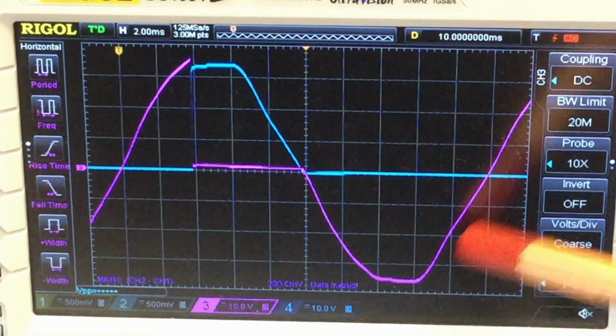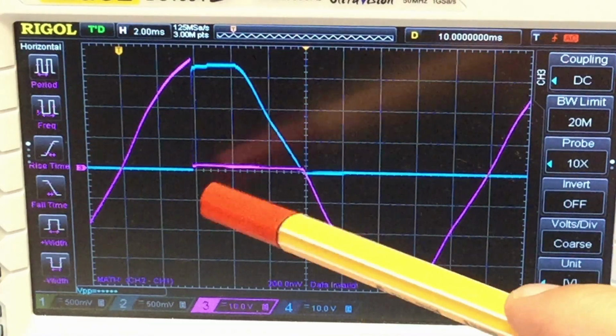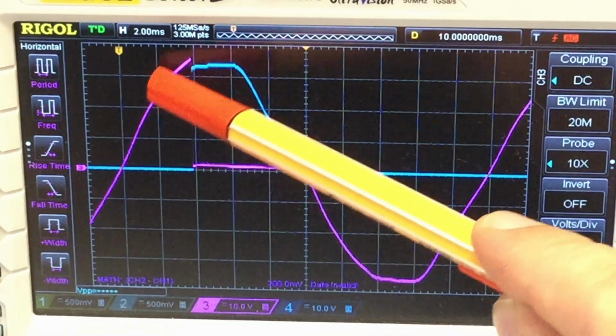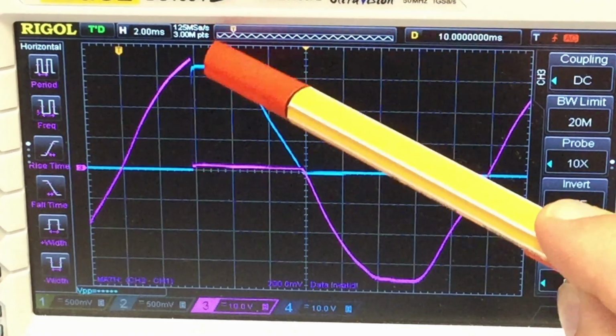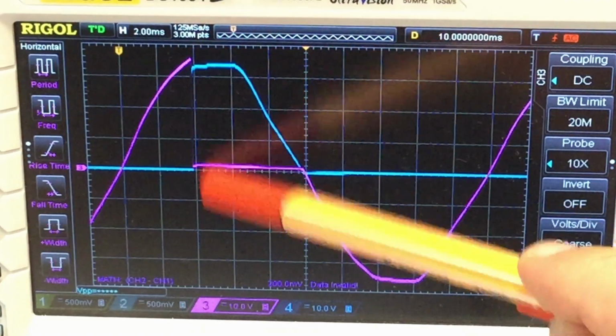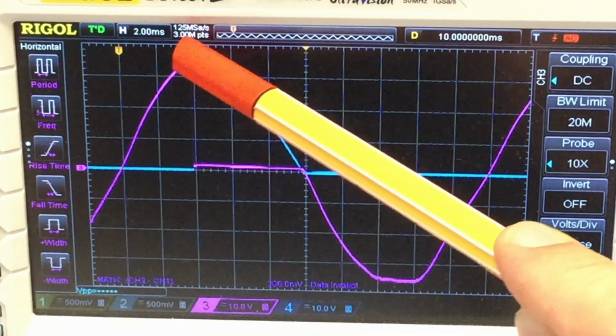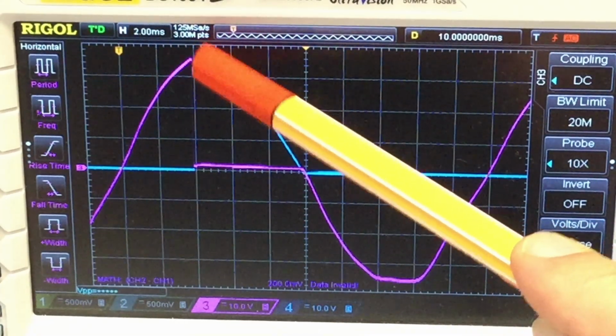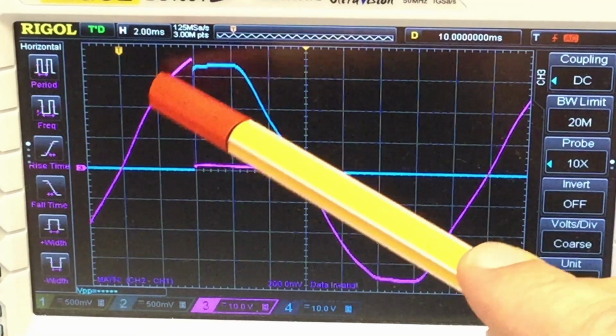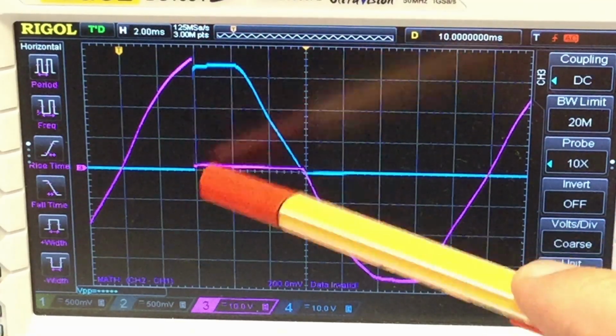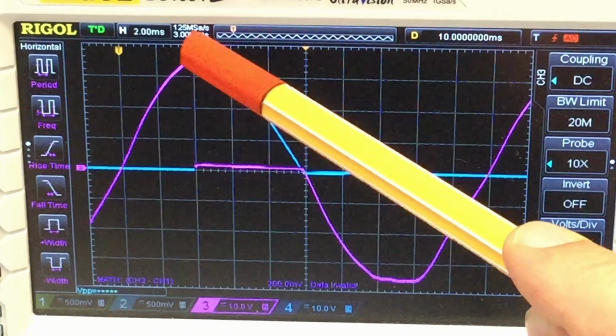Independently of which half wave is triggered, I always trigger at 90 degrees at the latest, because then the AC across the gate is the highest, and the current through the gate will be the highest.